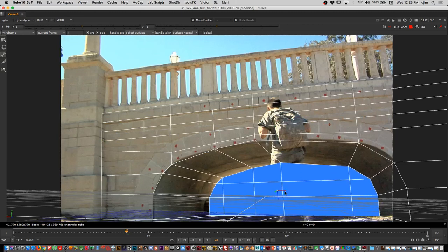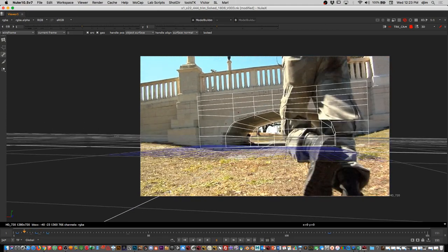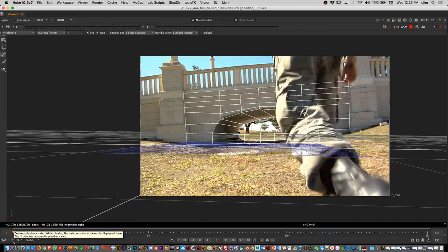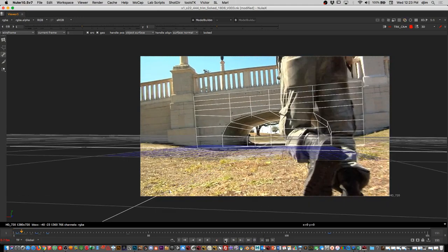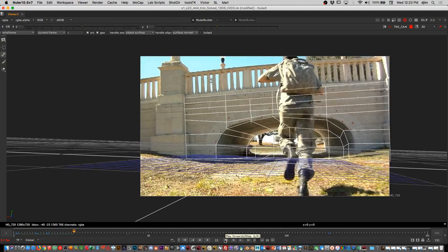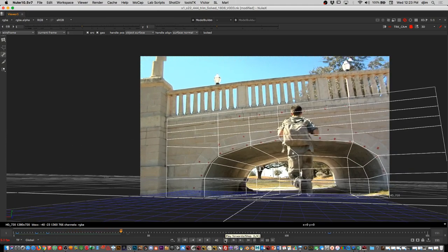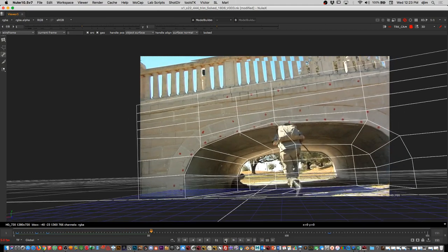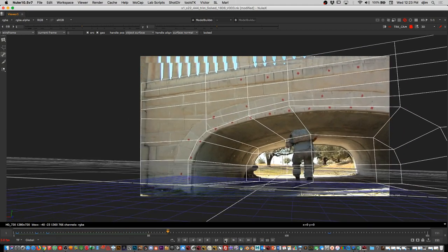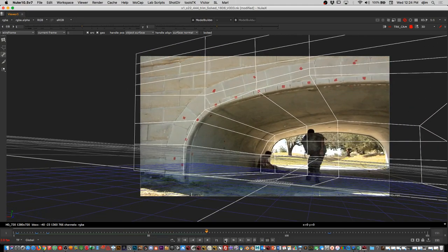That's telling me that I still haven't lined up properly the angle of my world. All right, now that we have that, there we go. We can see one side we didn't pay too much attention to. But now I have a very basic, rudimentary type of environment going. Now that side, on the right-hand side, I need to line up. And like I said, don't judge it until you finish caching it, because the footage will always be behind the model or the 3D. So wait until it caches, and then you will judge your motion. Make sure that everything is good.